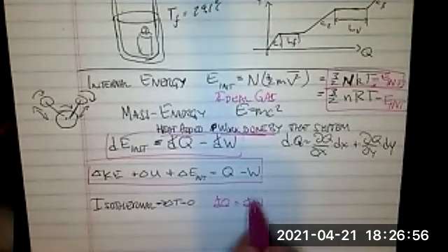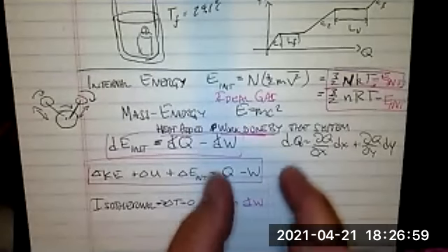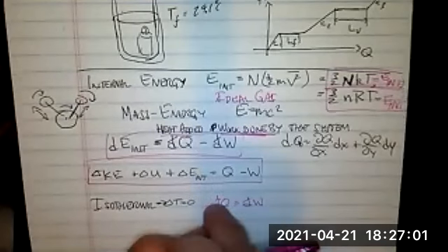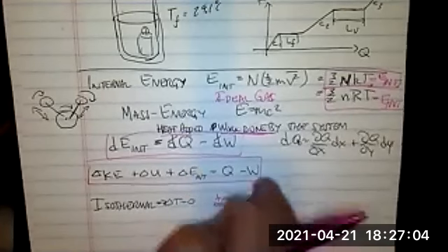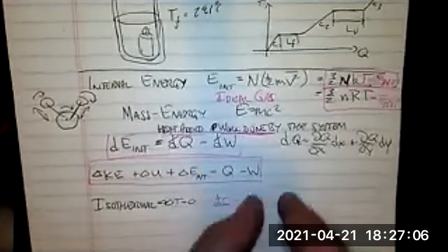So in other words, if you set up that cylinder with gas inside of it and a little piston head on top of it, and you add heat to it, if you have some little gremlins in there whose job is to work infinitely hard just to maintain the temperature not changing, and they're in tune with everything, then what they're going to do is rapidly move the piston head up and down as much as they can to prevent the temperature from going up or going down. And what would result is every bit of heat added going into the PdV happening.